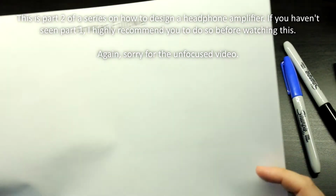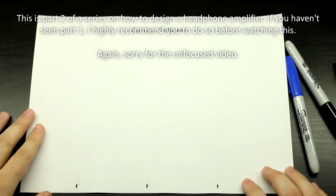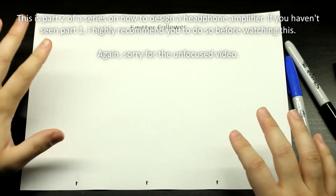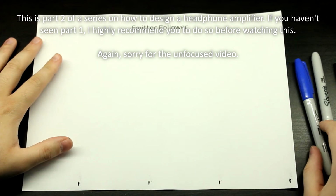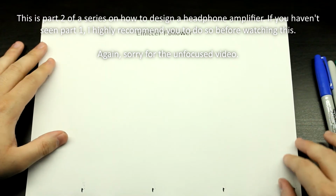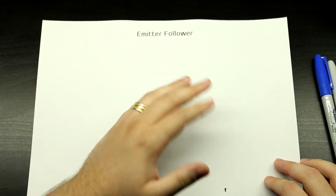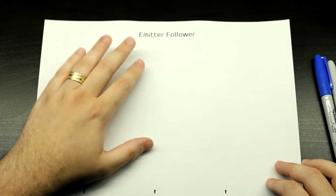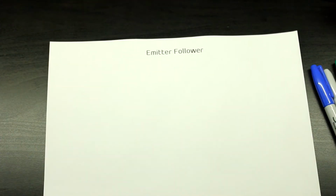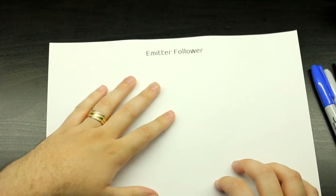So let's start by designing an emitter follower. An emitter follower is basically the simplest thing that you can do with transistors in terms of linear design. It's basically a buffer. It's going to get a high impedance input, and it's going to turn it into a low impedance output. This is going to be used as the output stage of the amplifier, and you will see these kinds of circuits anywhere when you need to drive a low impedance load.